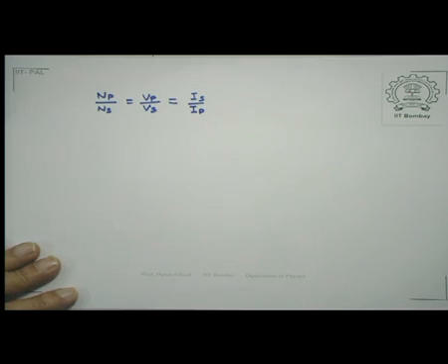So what it implies is that supposing we are using a step up transformer, then an increase in voltage would automatically come with a corresponding decrease in current. And conversely, if you are using a step down transformer, then the voltage will decrease, but the secondary current will increase. So there is a trade-off between the current and the voltage, and depending upon what our usage is, we have to worry about that. So let me illustrate these with some typical examples.